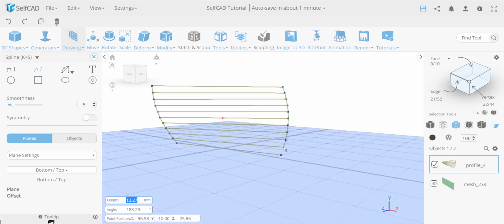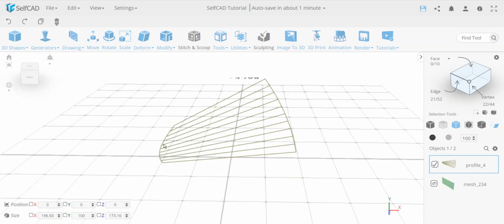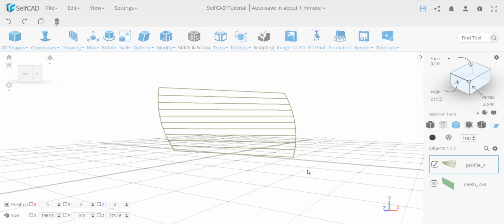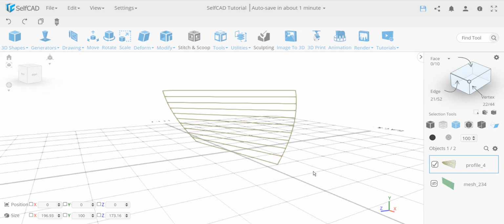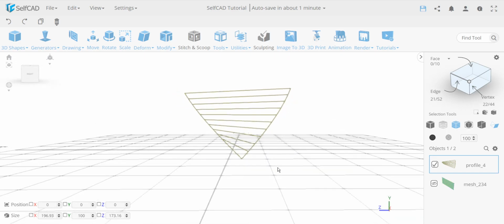this is not the actual scope of this video, but just to show this quickly, I can kind of complete this, and now I have this drawn, which is this shape. And again, this is not the topic of this video, to show how you can fill a shape like this and actually turn it into an object. But what I want to show here is that this requires something non-linear, which the first one was moved by 5, the next one by 10, the next one by 15, next one by 20, and then 25, and so on and so forth, because every time I repeat the previous transformation, and this ended up in something like this. So this is where deformation tools come in.